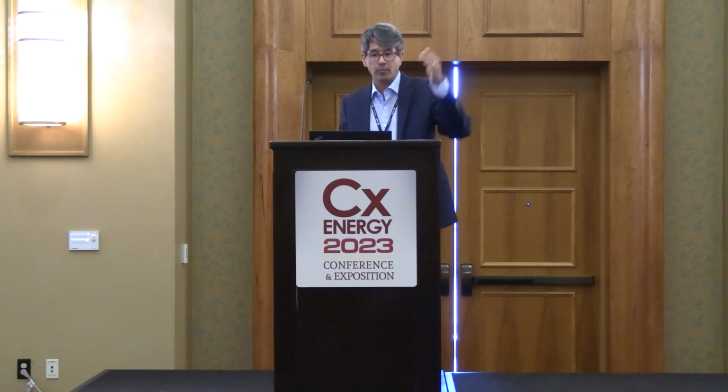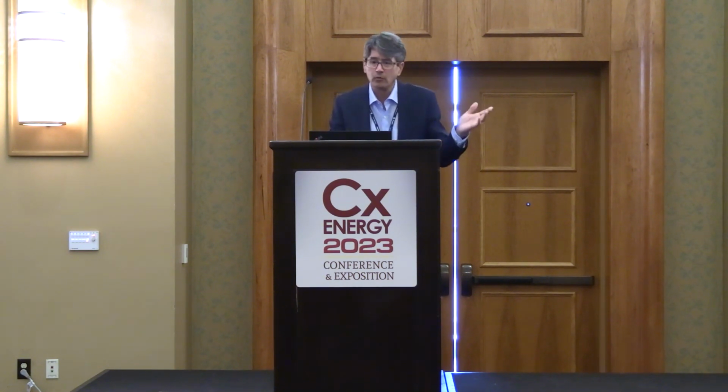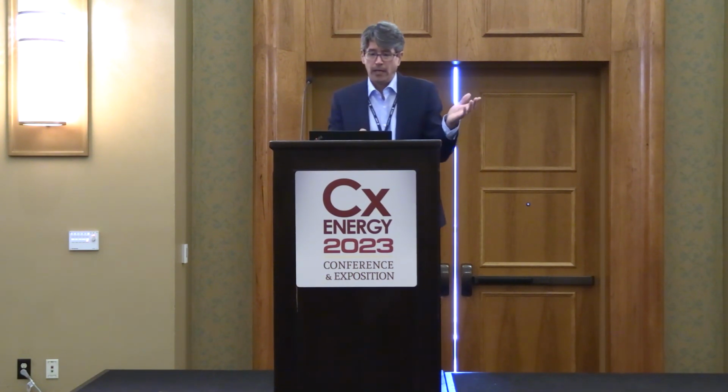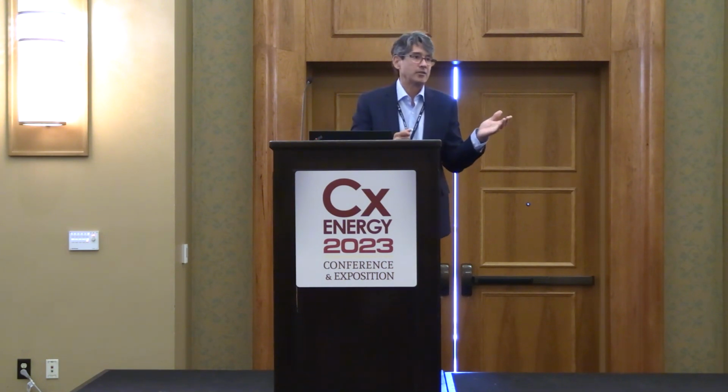So they started running the numbers and said, okay, over a 25-year period, I think it was 6 cents a kW and a 5% escalation in energy costs, that equated over the 25-year life of that building to $86,000 on just 6.7 brake horsepower. 30 schools, multiple fans, you can imagine what that number starts adding up to.